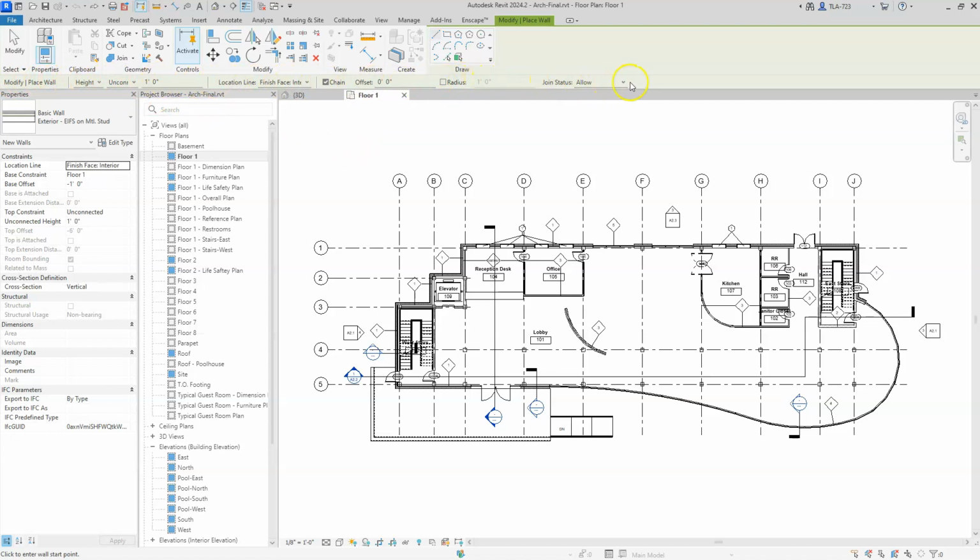and set before you start drawing that wall, because things like where it is relative to your cursor. Are you drawing from the center of the wall, the edge, someplace in between? How tall is that wall? Where does it start? Where does it end? Things like that. So there's a lot of different options up here that show up, and that's our options bar. So don't want to go much deeper than that into it. I just wanted to demonstrate that that thing is dynamic. It's not always there, and it will change based on what you're doing.